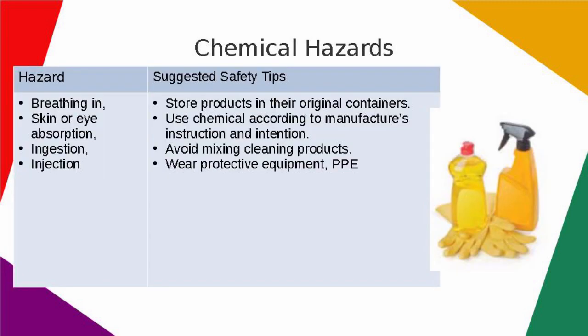Chemical hazard. Hazard: breathing in, skin or eye absorption, ingestion, injection. Suggested safety tips: store products in their original containers. Use chemicals according to the manufacturer's instructions and intention. Avoid mixing cleaning products. Wear protective equipment, PPE.